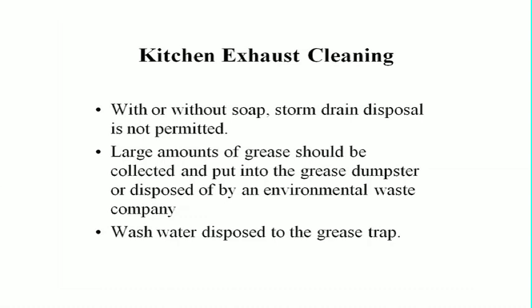Wastewater is disposed to the grease trap. If it's available, almost all restaurants are going to have grease traps. About the only ones that won't are office buildings where they put in a kitchen that might not have a grease trap. I've run into that situation two or three times. But otherwise, the method of going to the sanitary sewer is through the grease trap.